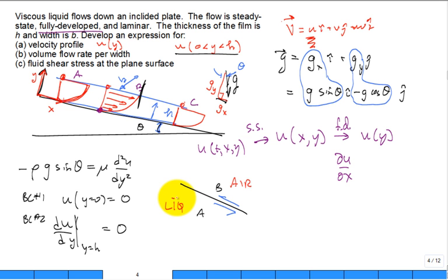So you can think about that air has a no-slip boundary condition, and it has to be flowing. If I wanted to sketch the velocity profile, it has to be flowing at the same speed as the liquid at that surface, so it has to have some sort of profile like this. It's kind of like dragging the air along with it, true?